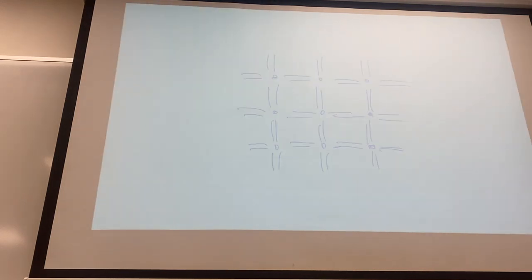Let's say we have dropped in arsenic at this spot, and now we've got, I'm just going to draw a line to represent this stray electron that's hanging out there. So it's got 5 electrons in its valence band. The fact that the 5th electron is not part of a covalent bond here means that it takes almost no energy for that valence band electron to pop up to conduction. So it's basically in the conduction band. You basically say this electron is free to conduct around because it's not being held down in any potential well.